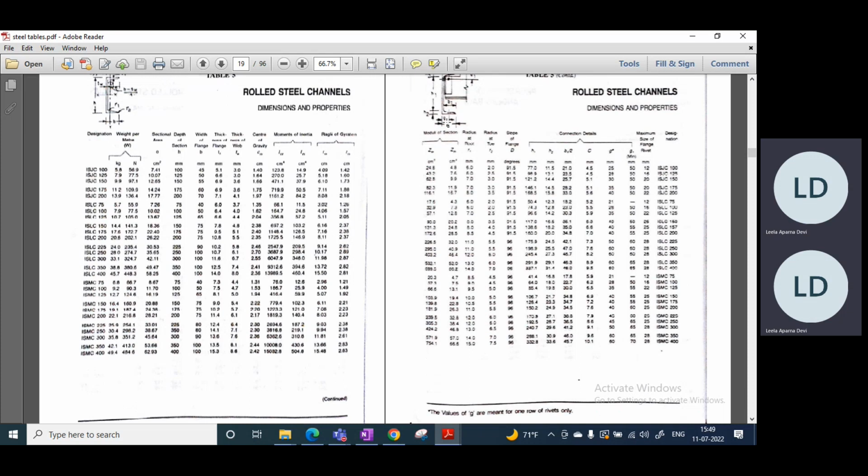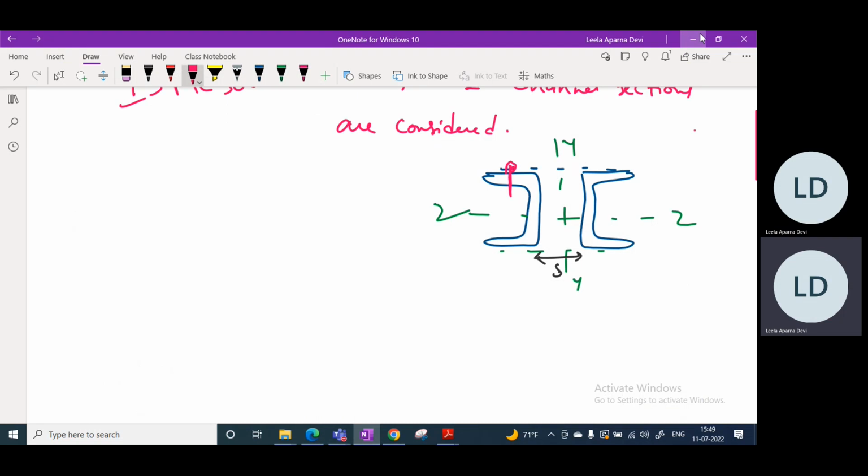So this G mentioned in this picture is from this back end to the position of bolt. So I'll represent here. Okay. So as we are having our bolts here, the space between these 2 points, that means to the bolt center, this will be the gauge distance for all the bolts.